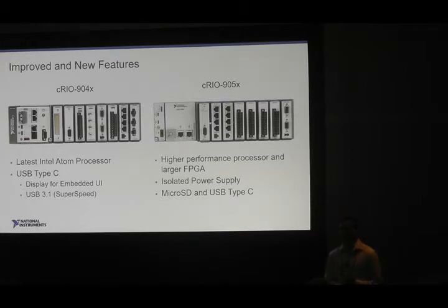But it also is actually how we're managing display as well. You notice there's no display port on board. That's now over USB Type-C as well. And similar to the display port that we had previously, we do have accessories that allow you to go from USB Type-C to VGA or DVI, or you can use many other standard connectors like HDMI as well. This allows you to take advantage of that embedded UI feature, so you can run a display directly from the controller itself versus having to go through maybe a PC or use something like a TPC, if you prefer to just drive it directly from the controller itself.